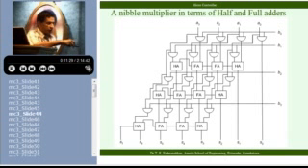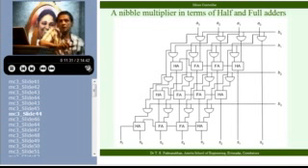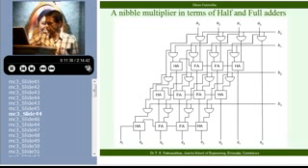With all that propagation delay, it will cause a lot of time delay for multiplication, especially as the number of bits increases. Whereas if you put it as a multiple input, multiple output function, do the complete table in advance and realize it as a very big single circuit, it is possible to reduce the delay.